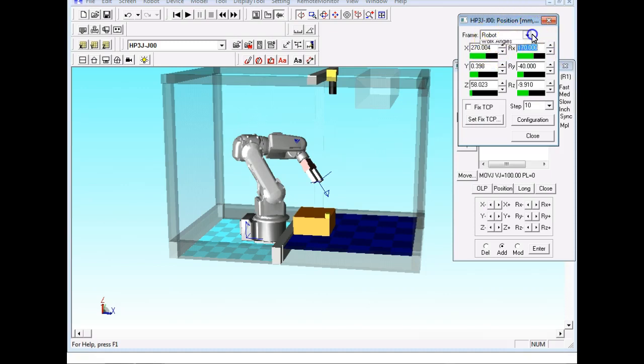So the Motoman robot stores these pulse readings right here. Just about all your other robots record the point in XYZ, roll, pitch, yaw. Or this one is. Oh yeah, just think about this. This is millimeters, so this would be micrometers. That would be 1,000 nanometers. So we have the ability to position this robot with the simulation within 1,000 nanometers.